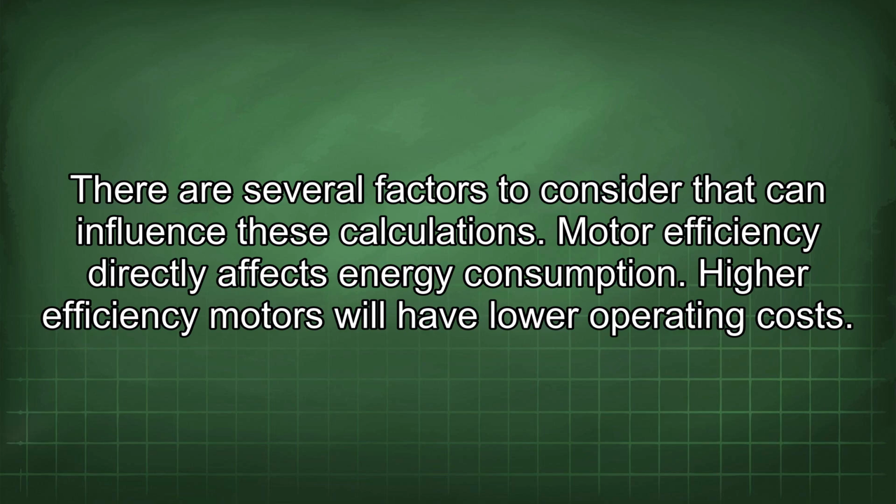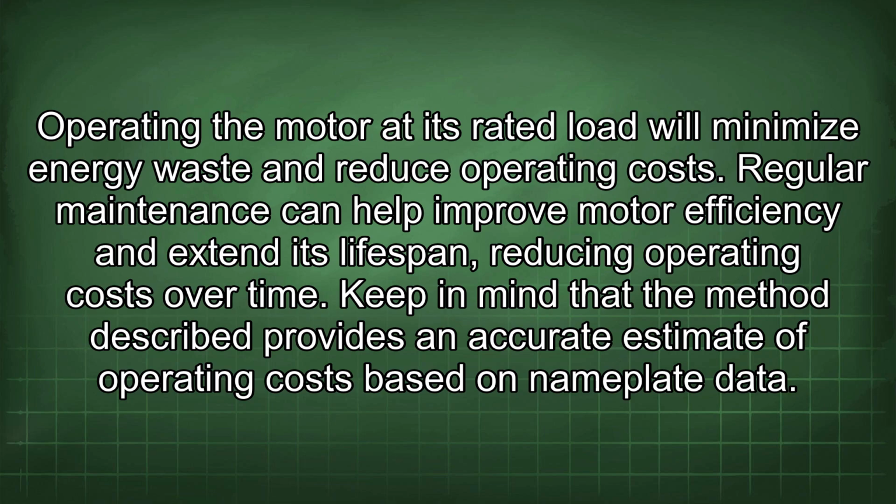There are several factors to consider that can influence these calculations. Motor efficiency directly affects energy consumption. Higher efficiency motors will have lower operating costs. Operating the motor at its rated load will minimize energy waste and reduce operating costs. Regular maintenance can help improve motor efficiency and extend its lifespan, reducing operating costs over time.